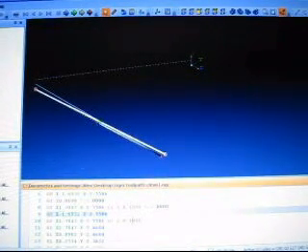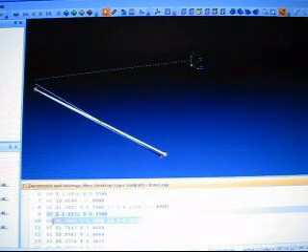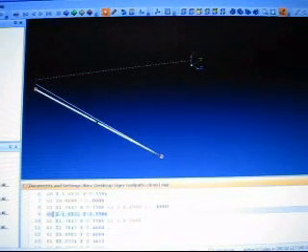And now I'm going to modify my Z to go another 1/10 of an inch down. Then I want to go back to where I started. So this time I'm going to copy both lines, but first I'm going to fix this from a G0 rapid motion to a G1. Okay, so now I'm all set.